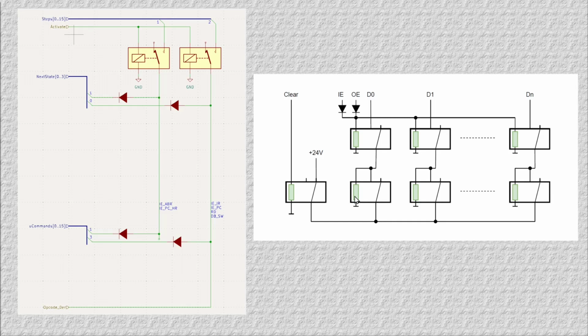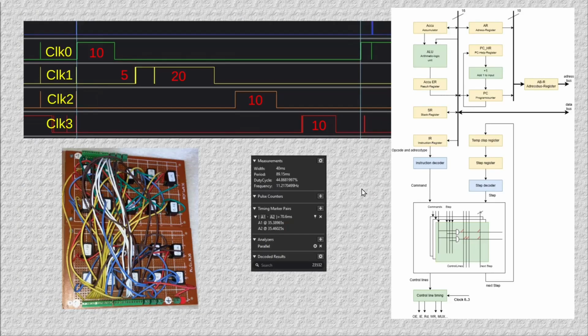And if we want to store a 0 in this bit, we have to delete the register and then we can store a new information. And because of this, we have to delete all registers before we can write them. And this is done during clock 0. Clock 0, clock 1, clock 2, and clock 3 are one cycle.